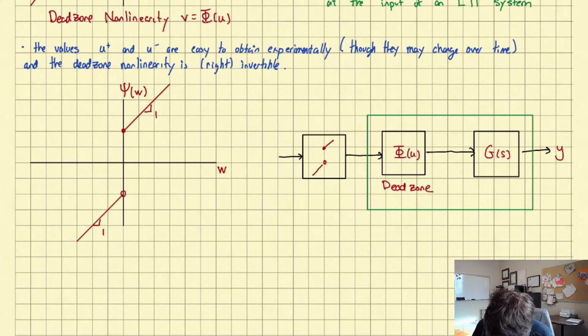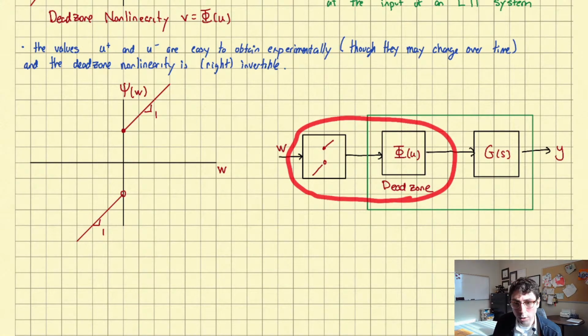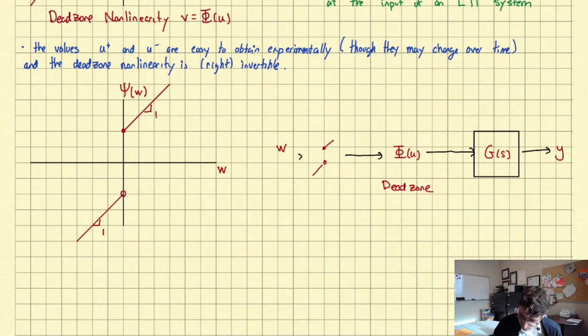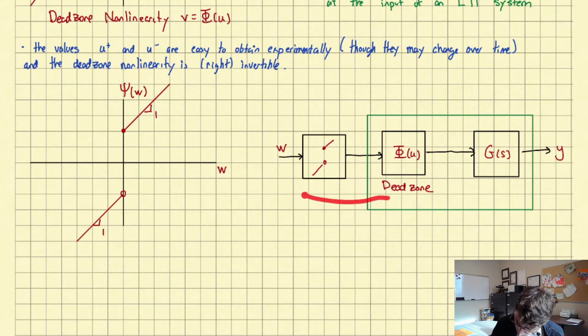Okay, and this is the signal that we will design for, right? So W now is the signal that your control block will produce. And ideally, certainly this will cancel the dead zone. So if it were indeed true in reality that static friction was a dead zone nonlinearity, then this cancellation would be perfect. And you'd be off to the races, linear system.